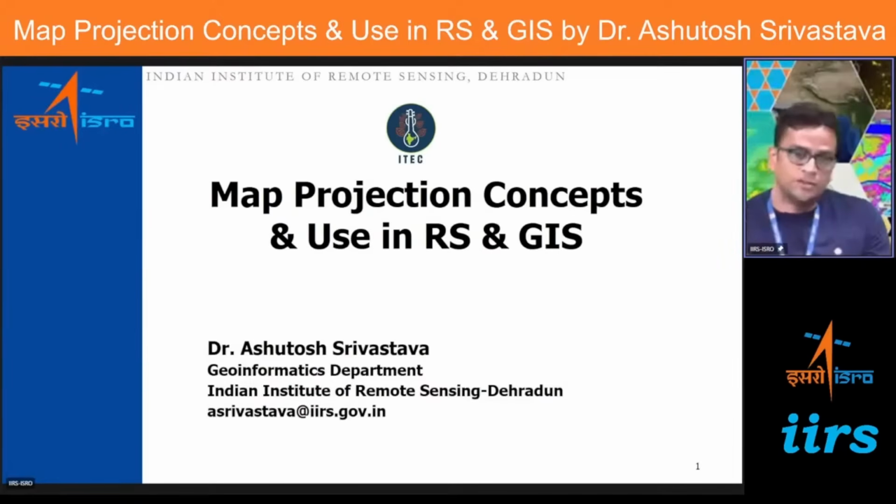But if this information is not in digital form, you have to digitize it first. Also, when this information comes from different sources, it may have different coordinate systems or projection systems. So the first thing we have to do is make a common coordinate system or projection system for all the layers. Only then, when we perform GIS analysis, will it be correct. If one layer has a different coordinate system from another, whatever analysis you do may not give the correct answers.